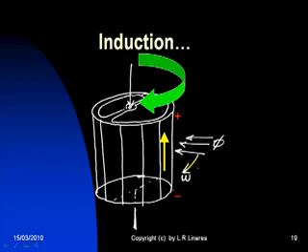Not quite as fast as the field, but fast enough. If it were to rotate at exactly the same speed of the field, there would be no more flux cutting, no more induced voltage, no more current, and of course no more torque. So that machine will rotate at a velocity that is slightly less than the velocity of the rotating magnetic field that we've seen before.